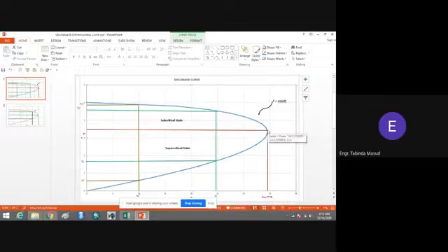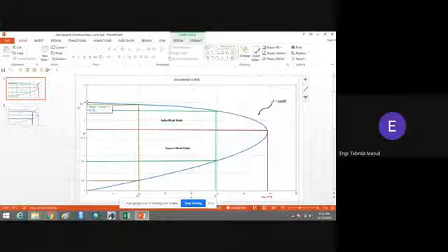And what was the reason? In the case of sluice gates, you can see that in the start, when the gate is closed, we have a high depth of flow and the discharge is almost zero. So this shows the same situation. At this point, we have the maximum depth of flow, and you can see that the discharge is zero under this condition.